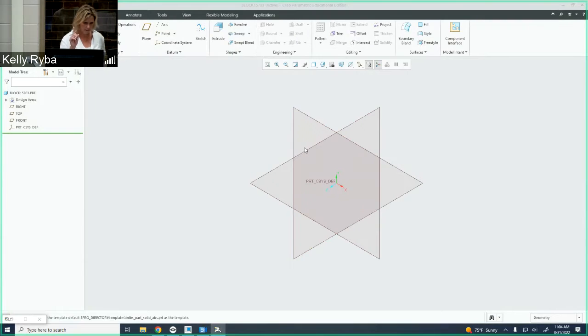Before I do this, sorry, I'm thinking ahead. We have a choice. We can go into Sketch or we can go right into Extrude. If you remember back from SolidWorks, if you've had that before, which you probably have, you can go straight into a function, and if you don't have anything drawn yet, it's going to start you off with a sketch because it needs a sketch first. And Creo is the same way.